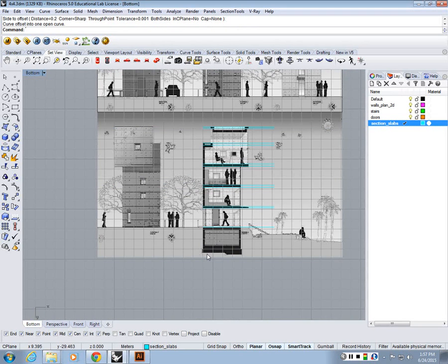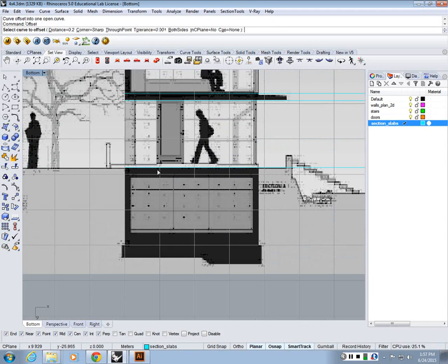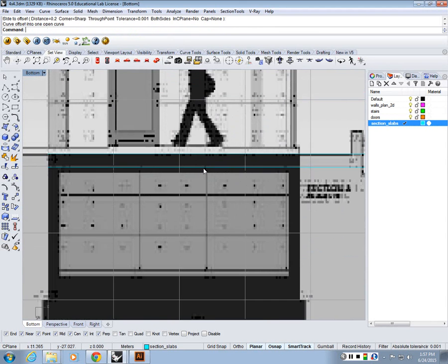So if I did offset, I can hit right click to run offset again. And it's enter as well. So you can get fast at using right click. Left click is mostly selection and enter to enter values. Right click is to execute and repeat. And offset distance 0.2. Well, this is a bit thicker, so let's do 0.3. So I found that guy.